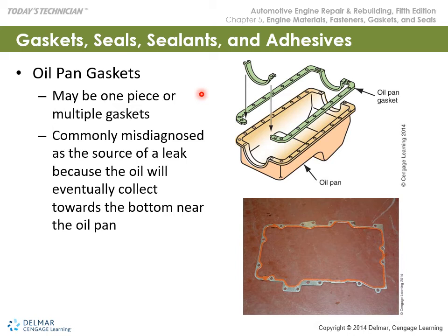You have to be careful that you don't over torque, and in this situation you see the orange elastomeric material on there. So when it's torqued correctly, that will compress against the flange of the engine block and correctly seal. So that's what you're seeing here in the bottom drawing. If that's torqued correctly with a crisscross pattern, the manufacturer calls that out in their service literature.